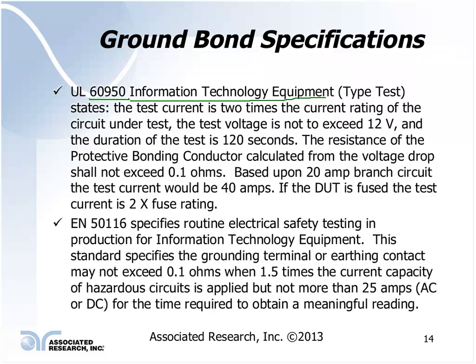One good test to demonstrate a ground bond test is to take a standard small paper clip, connect it up to your ground bond tester, and do a ground bond test on it. You pump 30 amps of current through it with a 200 milliohm maximum resistance.